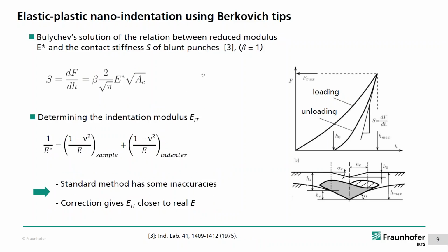And one step further, mostly you're not interested in hardness, because hardness is not a physical parameter, it's just an engineering parameter with which you can compare materials. You're more interested, for example, in Young's modulus, which is a real elastic constant of the material. And this you can achieve by this Bulychev solution. For this you use the unloading stiffness you determined one step before.